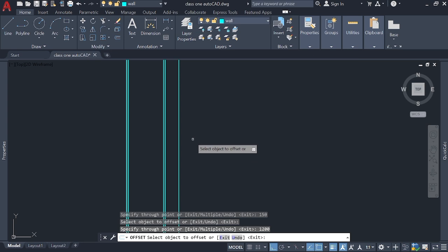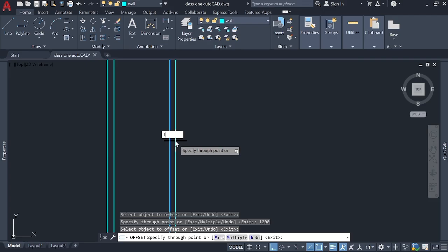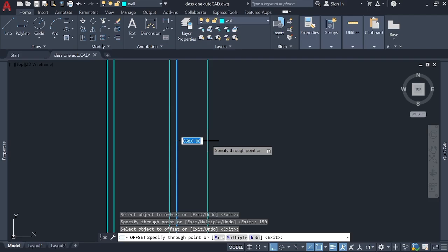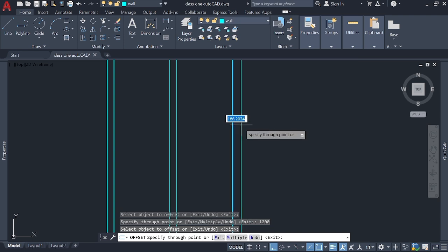From our drawing, we have, okay, let's put the wall. Click on it. Let's zoom in. Click on it. Put 150. Enter. Okay, let's check the dimension again. 1 2. Click on it. Drag to the right. Input 1 2, the length of the water closet. Click enter. Click on the line again. Drag it out. Put the wall with 150.